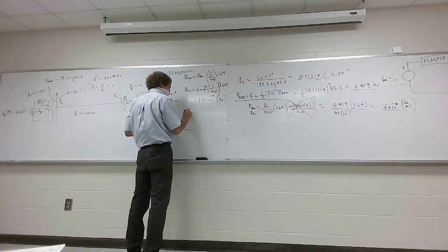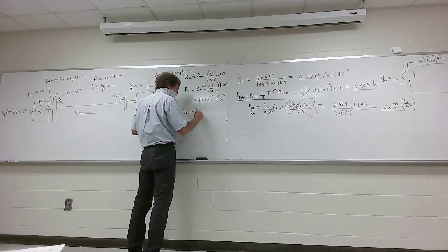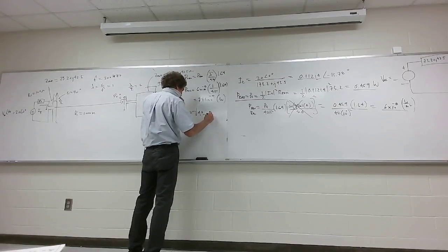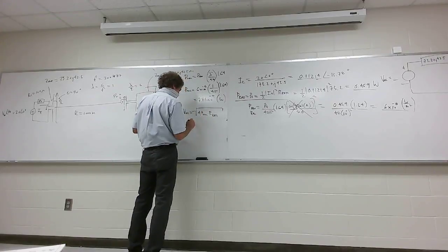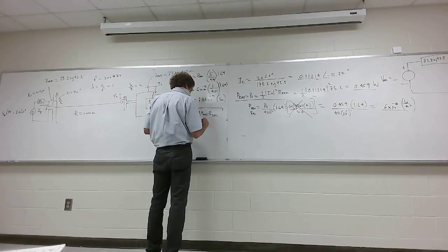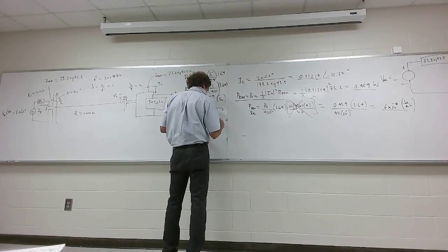The V open circuit used over there will be the square root of 4 times P received, times the actual radiation resistance. Now for us, it would be the square root of 4 times P received, or times 7.83 times 10 to the minus 9th, times 73.2 ohms.